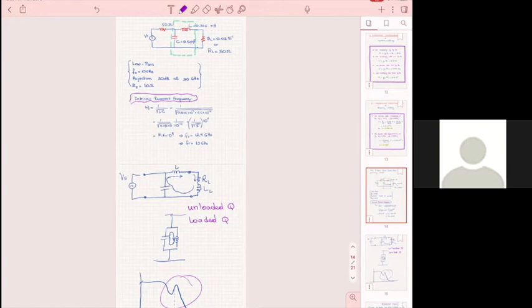If your load is resistive, then it damps the resonance and your loaded Q becomes very low. A strong resonance gives very high Q, all right? A damped resonance, because you have a resistive load that absorbs all the energy, all of the energy that goes between L and C is dissipated by the resistor, then your Q can be very low.